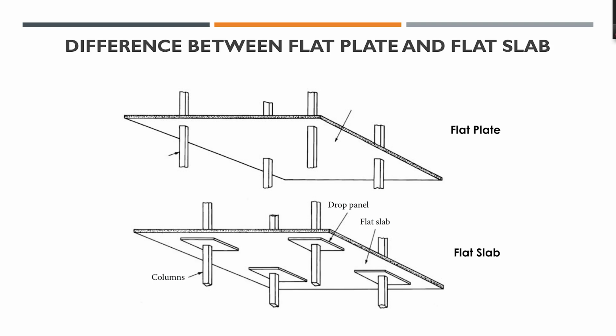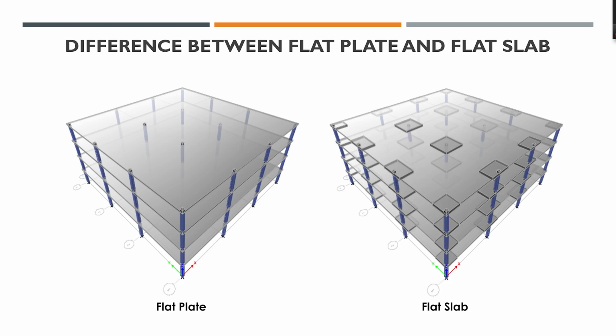Okay. And normally, like I mentioned to you before also, building codes do not allow this to happen. So you have to create a building frame where all lateral loads are taken by shear walls or alternate systems. And gravity load does not participate in the lateral load at all. So columns and slab do not do anything. It's the building frame, the shear wall, or the framing system that does that. And we will talk about that. So this is just a figure.